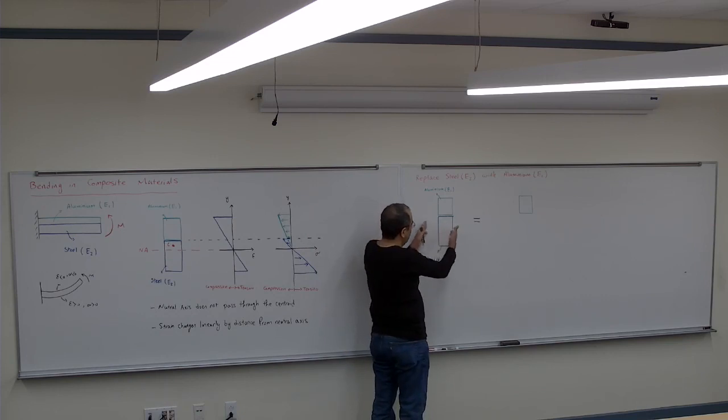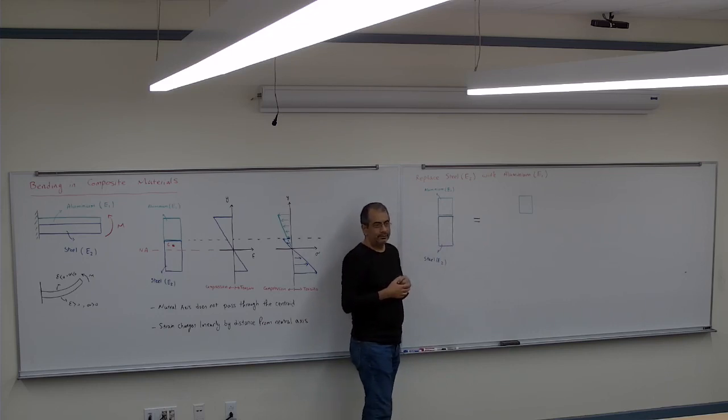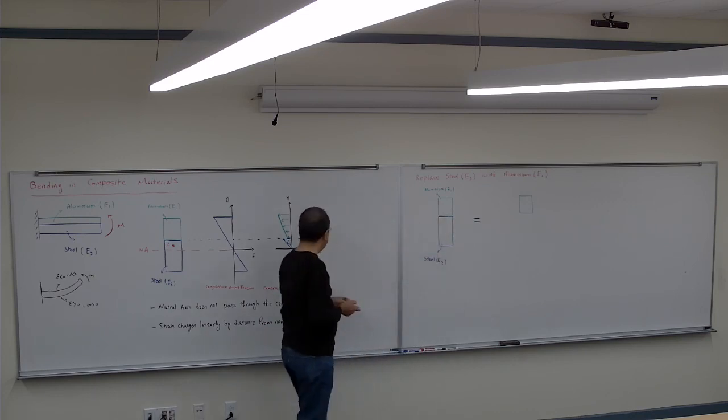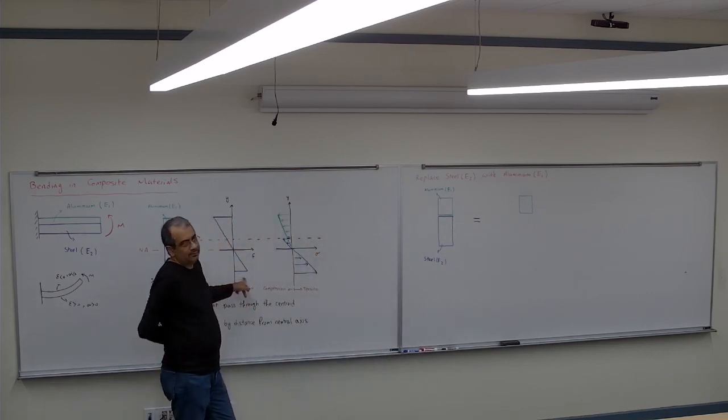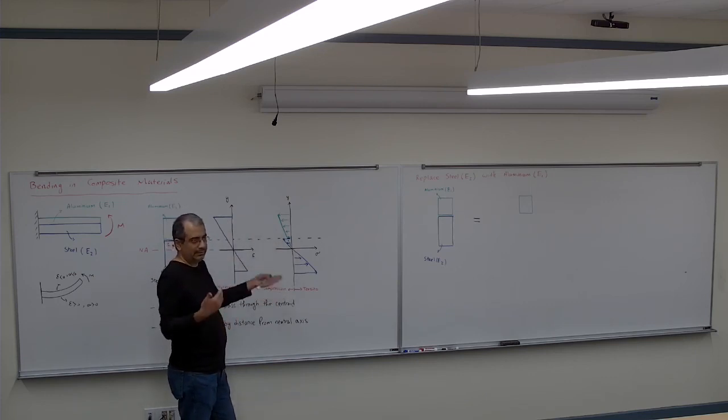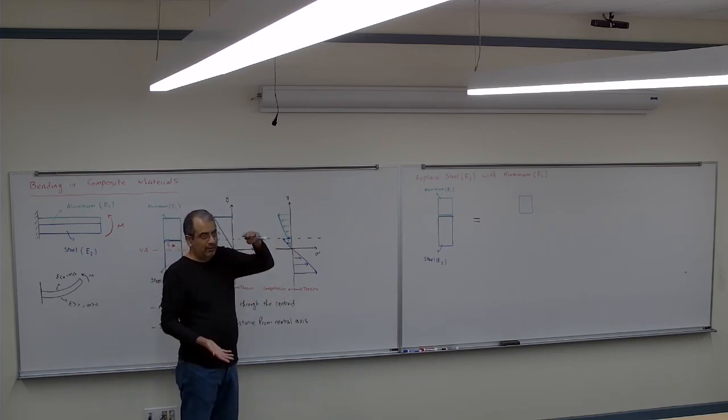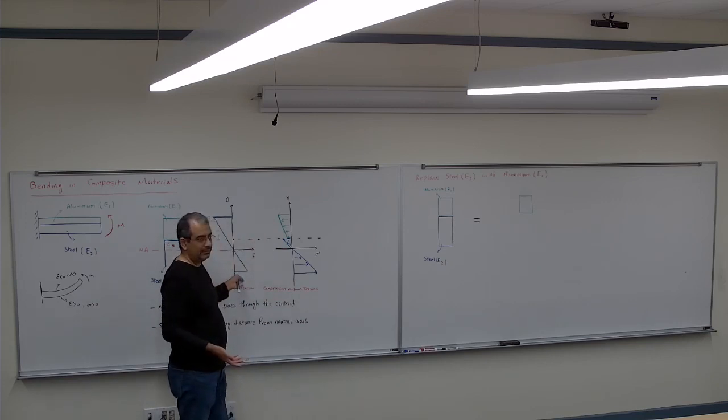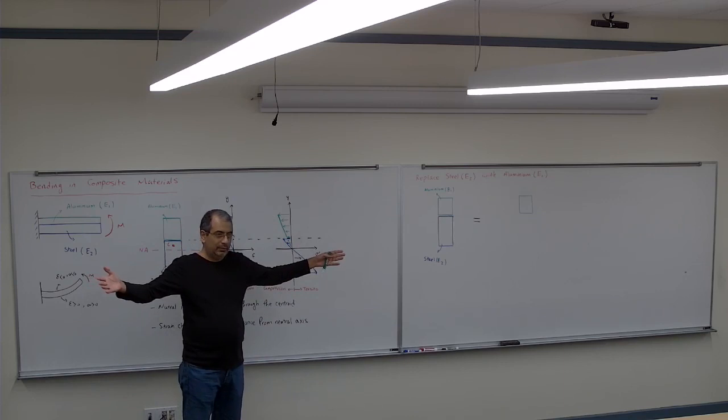If I want to put more aluminum, I'm going to put it in the width or in the height or both ways. You probably should do both, but in this case, do it lengthwise, like height. So if I increase the height, what would happen here? My strain is not going to be the same as before, which I don't want. I want to keep my strain exactly the way it was so I can see what I'm doing. So we never increase the height, because if I increase the height, we are going to mess up the strain. We only increase the width.